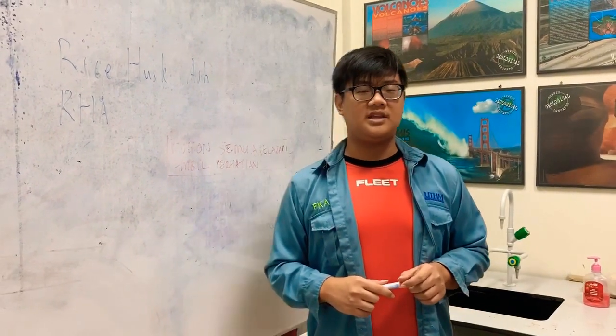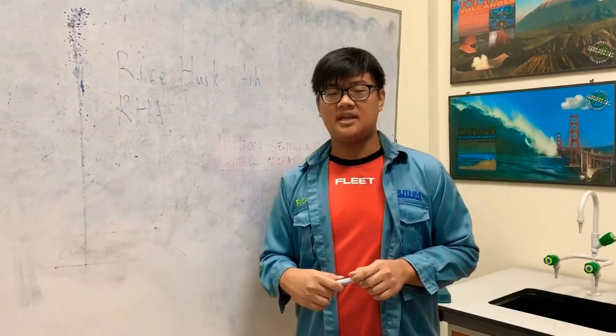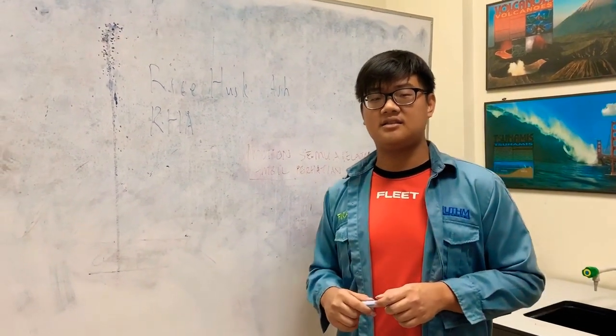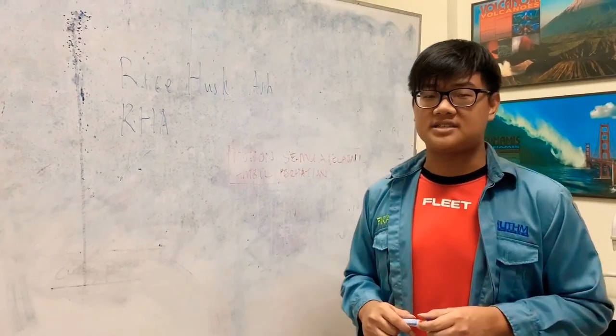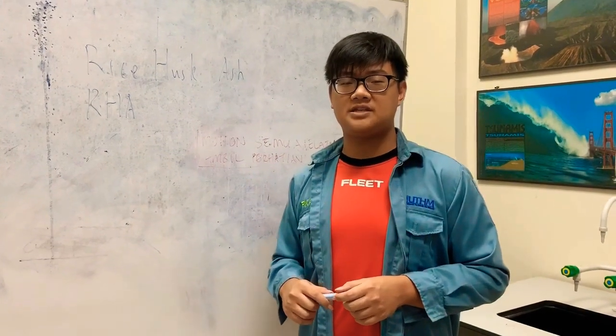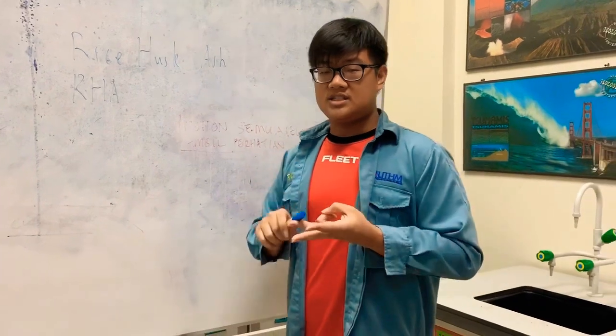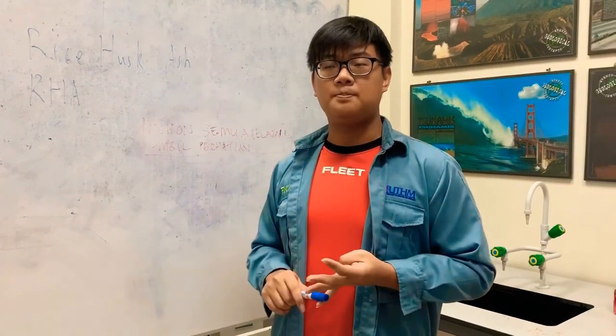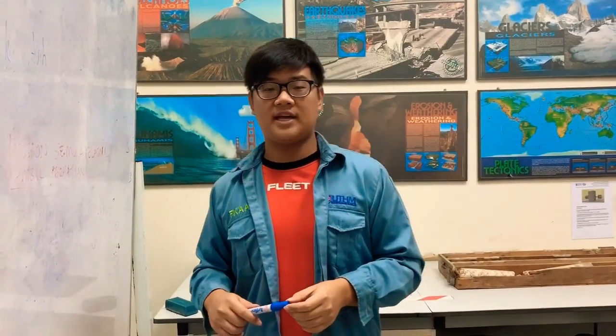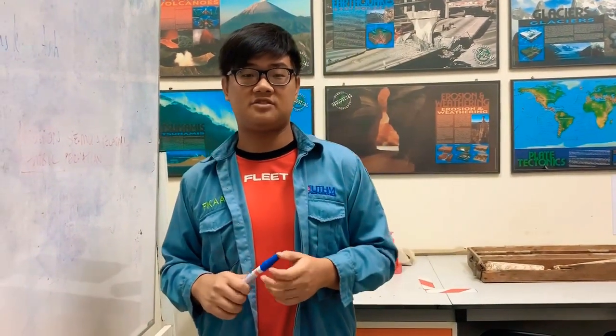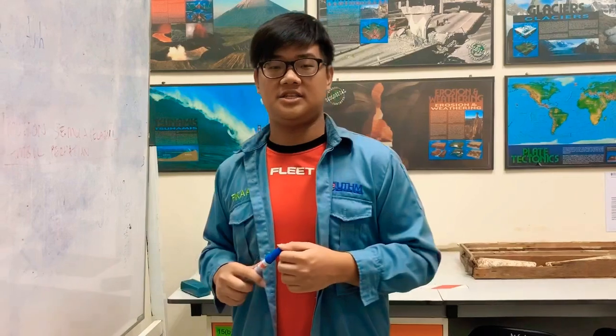It has been proved in his research that it can help to improve a few soil property parameters such as liquid limit, plastic limit, CBR value, and so on. Besides, it is proved that 20% RHA mixed with the soil is the best ratio for stabilization.